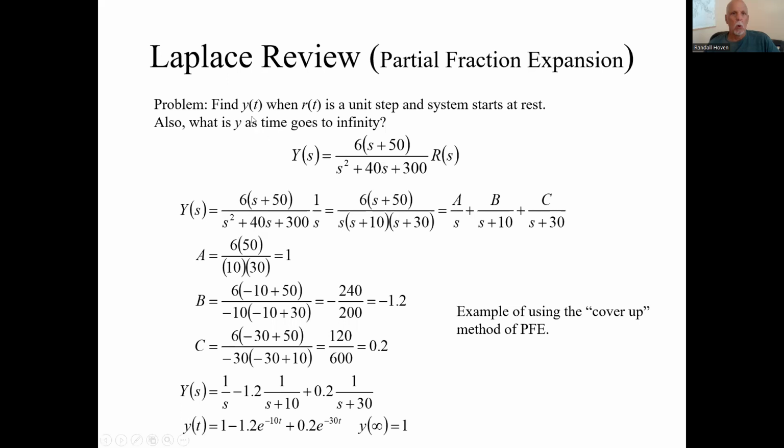What is this y of t as time goes to infinity, where we're given the transfer function and the input? We had to do this fairly tedious inverse Laplace transform using partial fraction expansion to get the function and then take the limit. Finally, you could take the limit of this answer, and the answer was 1.